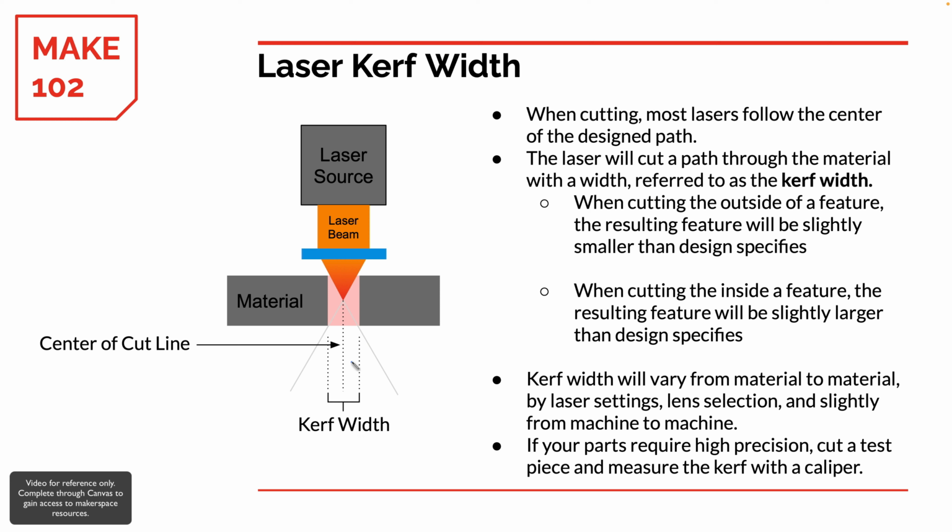Now, this will vary from material to material, and it can vary from laser to laser, and it certainly will vary from lens to lens. So if you are cutting something that has particularly tight tolerances, you may need to measure the kerf width before you cut your final part to come up with the actual dimensions that you want to cut.